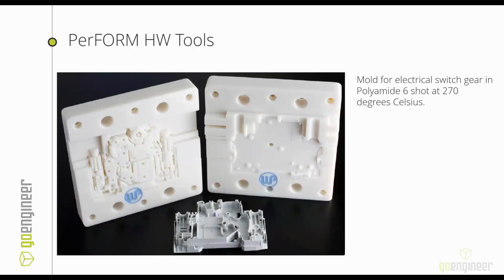And with that, instead of having a small vat of resin you pull your parts up out of, you actually have a large vat of resin you build your parts down into. That means you have a much higher startup cost, because you have to have gallons and gallons of resin to fill your vat to be building into. But if you're a company that does a lot of injection molding tooling, that could be a great option.